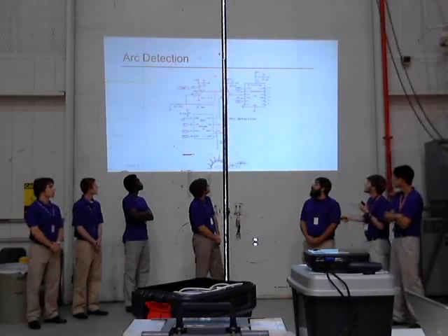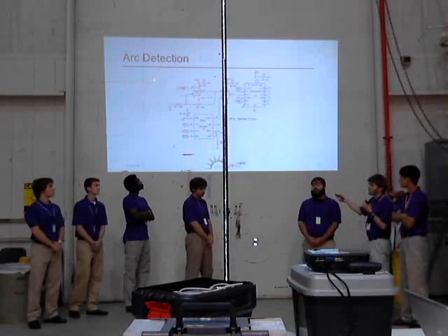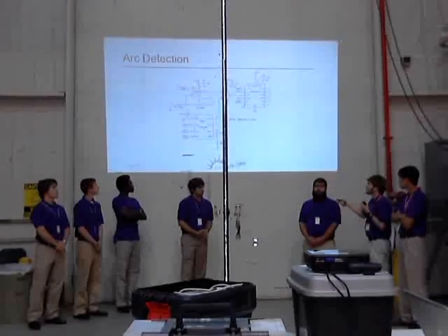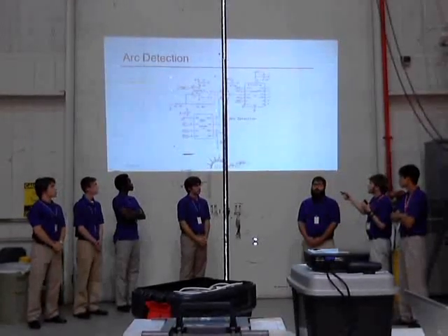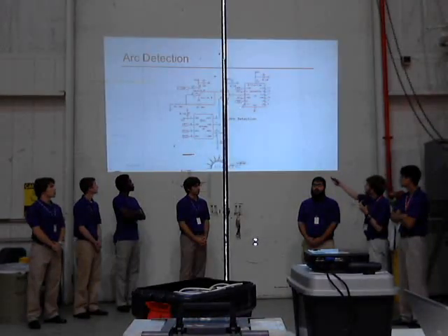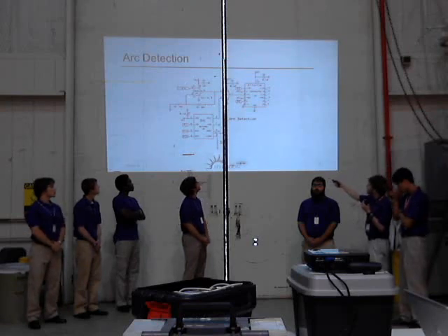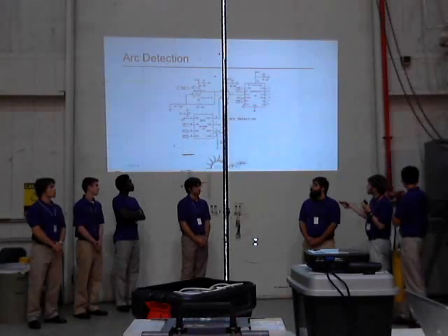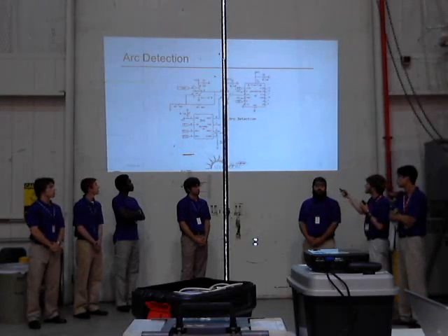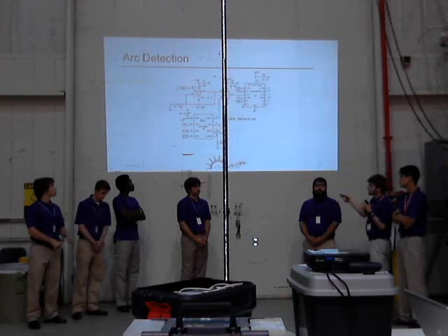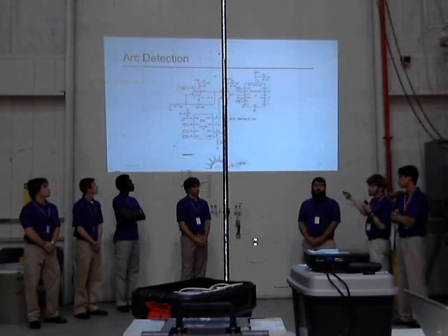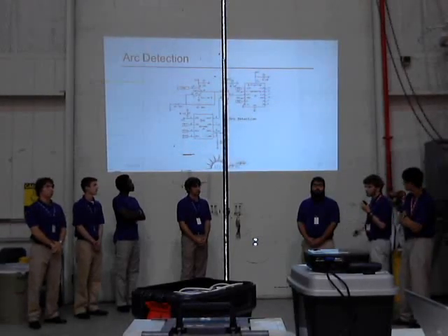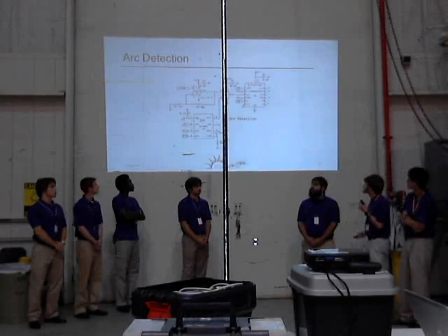How we accomplish the arc detection is we have the current monitor pin of the HVDC, which we amplify with a gain of 5. It's compared to a variable voltage from another digital to analog converter, and whenever the current exceeds a certain threshold, a spark is considered to be detected, and it toggles a D flip-flop to register that there has been a spark that occurs.